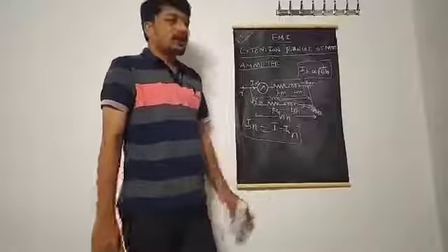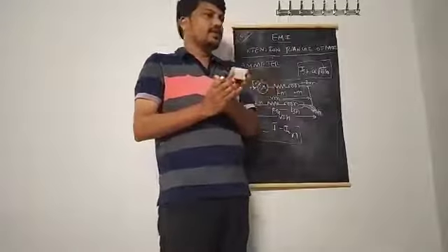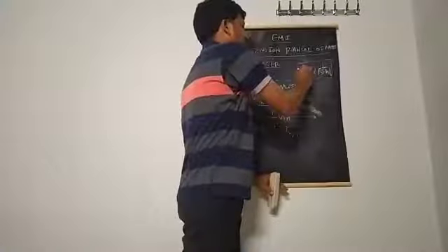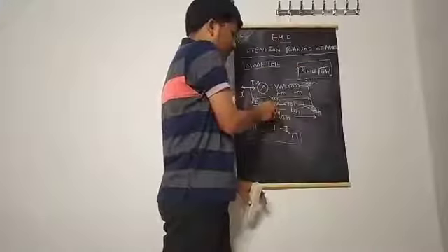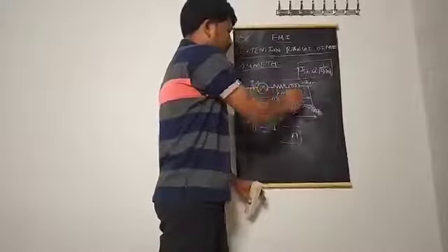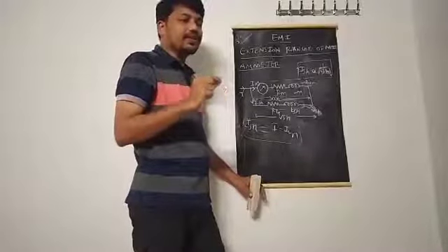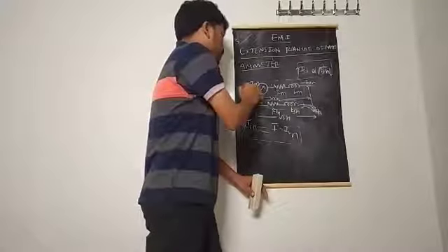Also, to extend the range of a moving iron meter as an ammeter, the shunt resistance is generally taken as a lesser value of resistance. Then we can measure a high value of current. If the shunt resistance is low compared to this path, then by the fundamental concept of electrical circuit theory, the current always searches for the low resistance path. Therefore, current won't be allowed here.